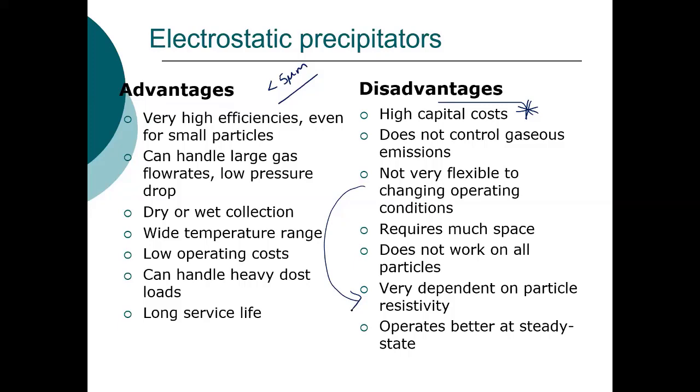The one I mentioned was a major change in the coal, so the source material, but variable properties of the gases can also have a detrimental impact. They don't work very well on sticky particles, particles like tar, gelatinous material, hygroscopic material that tends to stick to things. And they can also be a potential fire hazard.